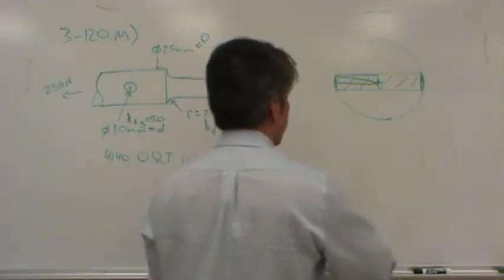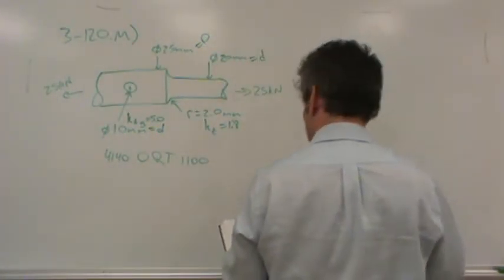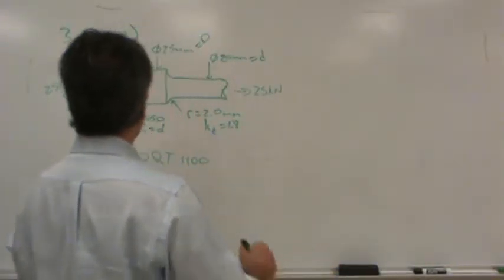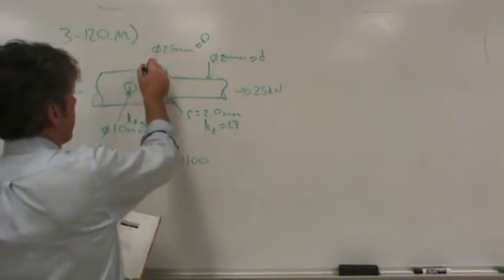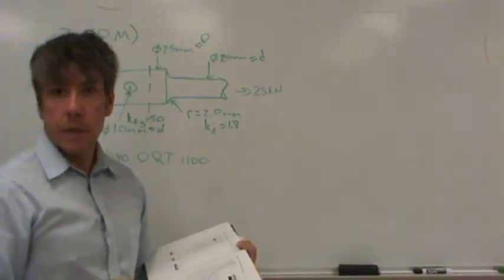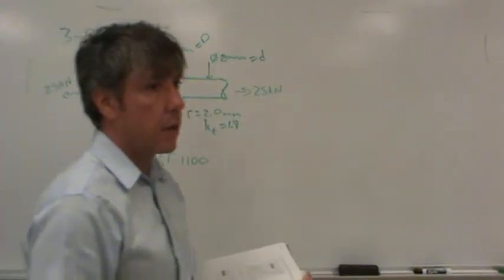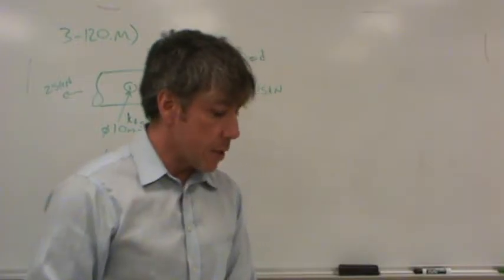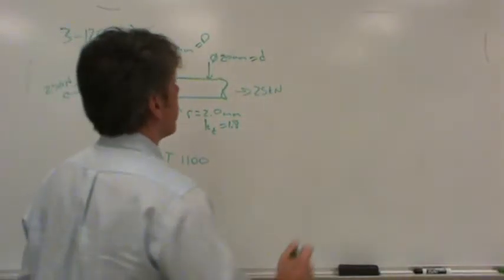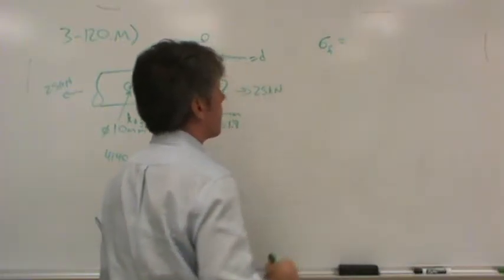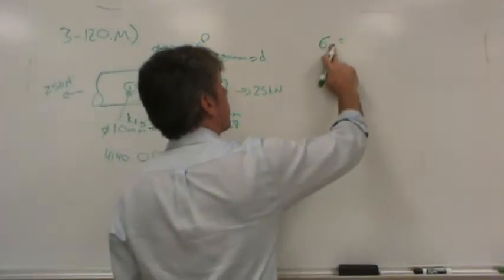So it's a good thing that it's based on the stress in the gross area, because now all we have to do is calculate the stress over here, and that'll be fine, where there is no hole. Does that make sense? There is just a circle. Okay, the area is just a circle. All right. So let's calculate the stresses in each of these sections. So let's see, the stress at the fillet, let's just put a subscript F so we know which part. Better yet, let's do it this way.